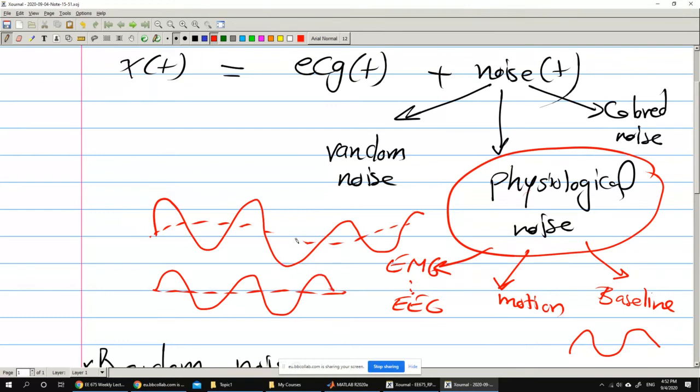This can happen because of several things, but usually you have a capacitive effect, related to the way the system is designed and the way the electrode is attached to the patient. The problem is that we have difficulty interpreting the ECG, because in order to diagnose the ECG, the doctor looks for the level of particular segments of the signal. If the level is elevated, it can indicate a certain disease. If it's depressed, then it's another. So baseline drift like this is a big problem.